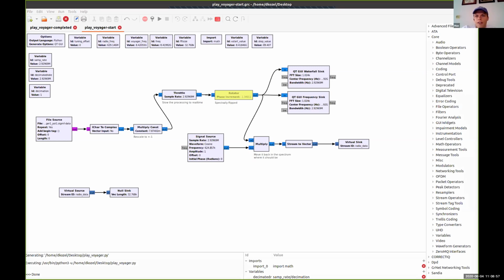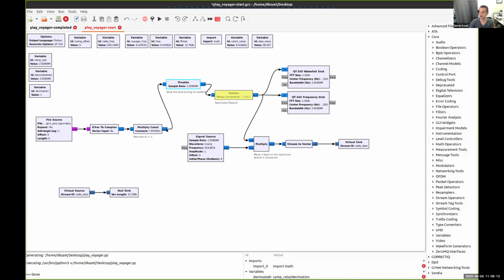A few of us are having errors. Do you have any comments on getting an error about a missing tag and it's a less than sign? When you draw a connection between blocks, you probably have a curved line or a straight line. You're probably on GNU Radio 3.7. And the file I sent out is for 3.8. I was wondering if that was going to be an issue.